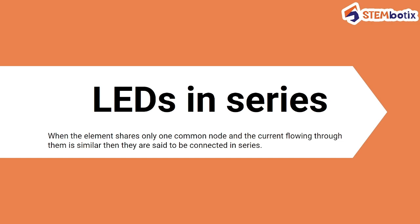When elements share only one common node and the current flowing through them is the same, then they are said to be connected in series. So this is the series connection definition which also applies in this particular section. So your LEDs would share only one common node, but the current flowing through all of them would be the same, and hence you can say that your LEDs are connected in series.